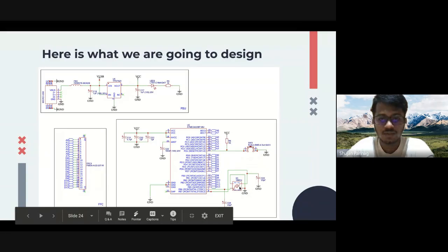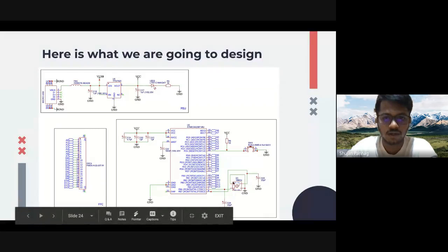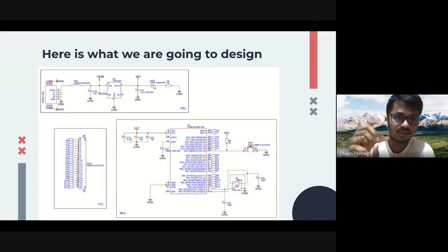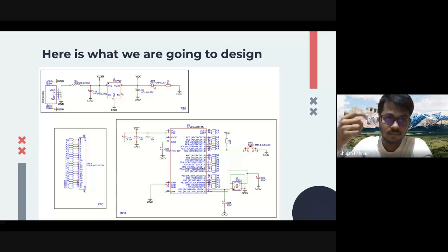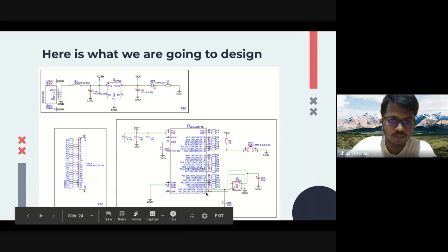When the crystal is modeled as an LCR circuit, you're increasing the capacitance, so you're making it more inductive, thereby increasing the phase shift. So internally, between these two pins, it's 180 degrees.